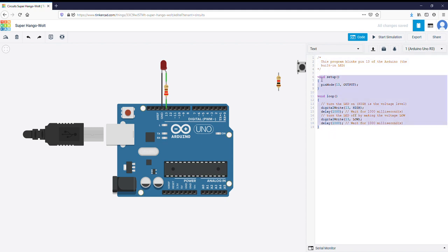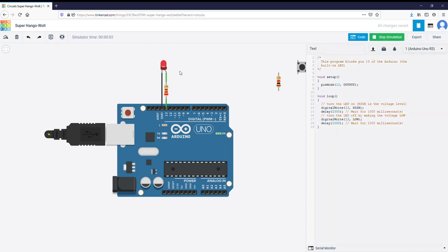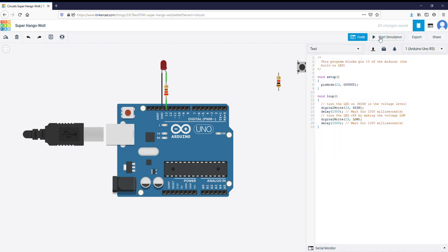this is the code, and without delay, how about we click start simulation and see what this does. Okay, we can see that this LED is blinking on and off, on and off. And oh, there is also this small LED here. Wow, I didn't notice this. We can stop the simulation, and TinkerCAD is really emulating Arduino very well, because the Arduino board also has a small LED here, and it seems like everything is here. So what this code does is blink this LED on and off.